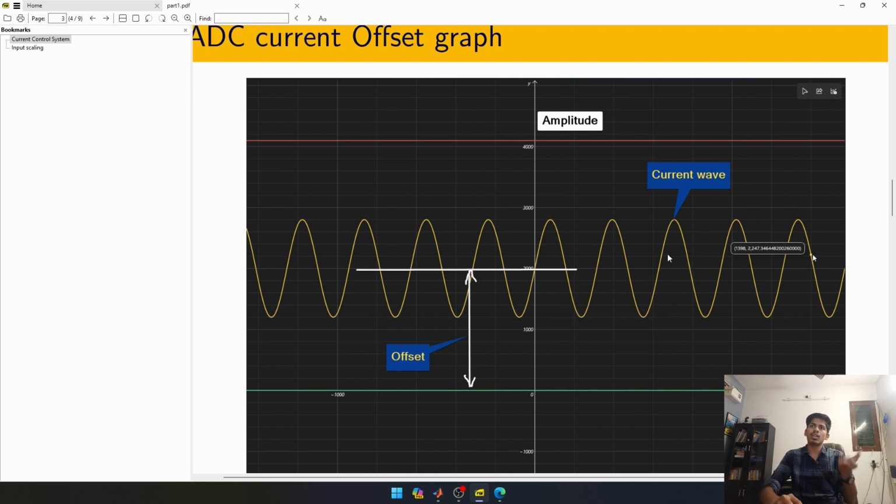So this is our motor current, which will be scaled appropriately. For example, if the motor current is 2 amps, there will be a shunt resistor connected across the motor terminal, which will give a proportional voltage according to the resistor we put. That voltage will vary in proportion to the current flowing into the terminals. So we will scale it appropriately to make sure we don't damage the ADC of the input port of the C2000.